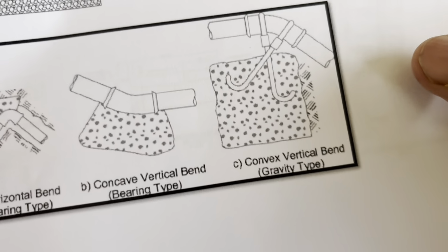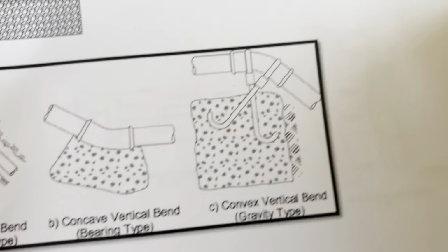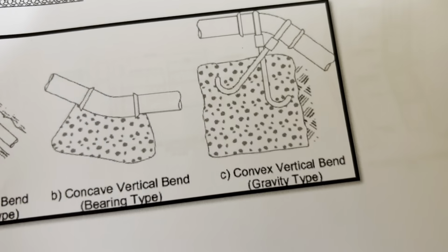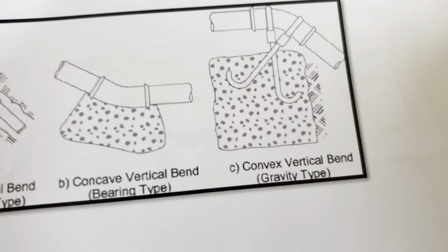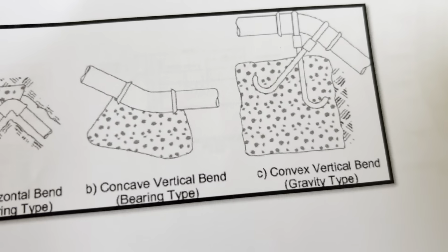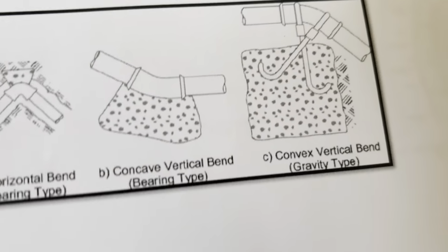And same here, we may have some pushing up system, and number C, pushing up load, and we have some gravity or just heavy item here, and we have an anchor to the piping system. It holds the whole system down and prevents thrust load damage to the system.